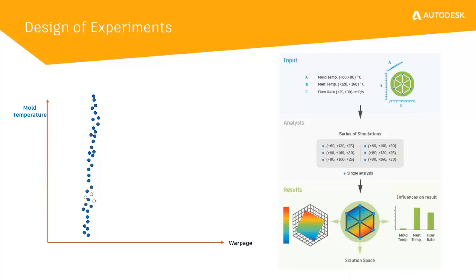In order to explore the wide range of process conditions and drive optimization, the DOE setup allows the Moldflow user to select which process conditions to vary. All of the processing controls available in Moldflow, such as melt temperature, water inlet temperatures, filling controls, pack pressures, and times, can be used as part of the DOE.